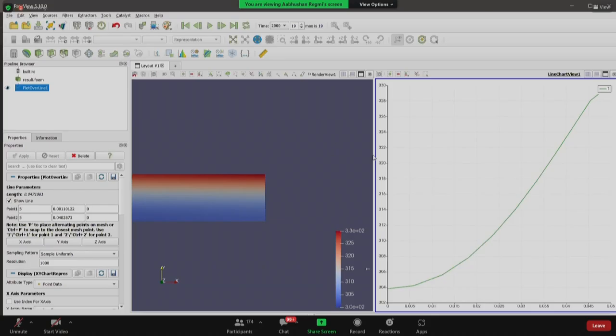Suppose in my case, I am getting this error when I try to run using buoyantFoam: keyword pimple is undefined in dictionary home/my run directory/OpenFOAM/heatflux/system/fvSolution. So do I need to change something in the fvSolution itself? Yeah, that means there is something wrong with the fvSolution. Instead of PIMPLE, it may have some other name in OpenFOAM 10. That could be the thing.